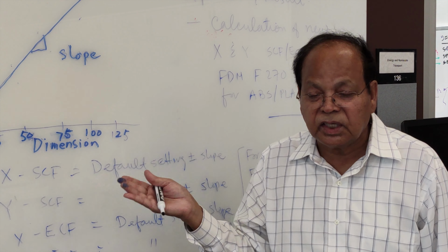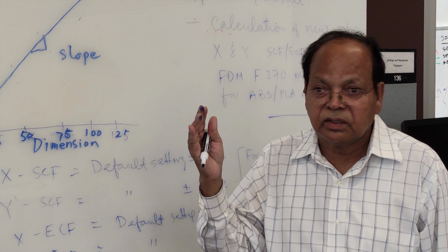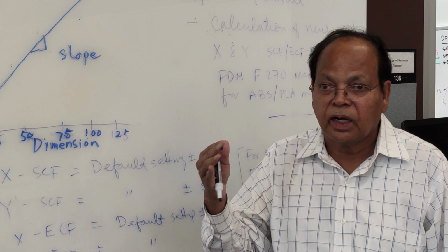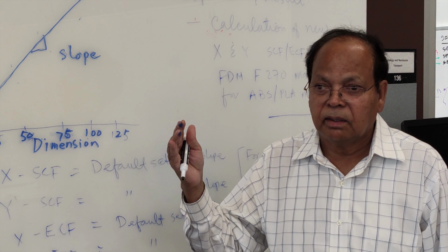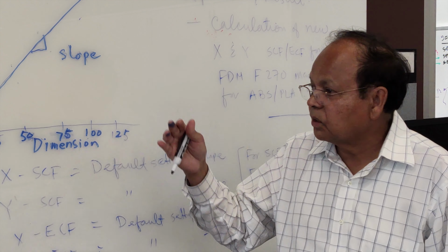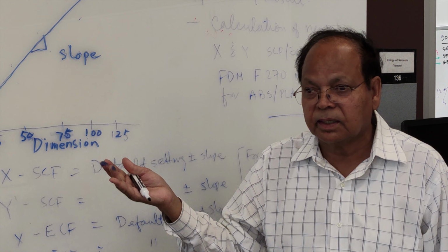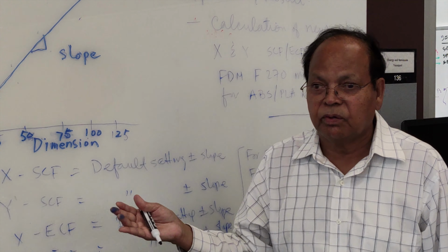Anytime you change the materials or you change the FDM head, you are required to make this new calculation so that the parts that you make after that become accurate.